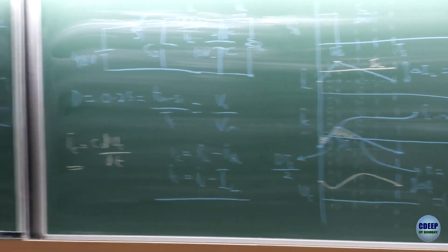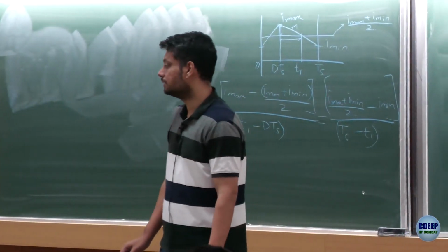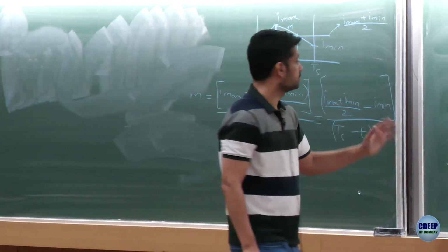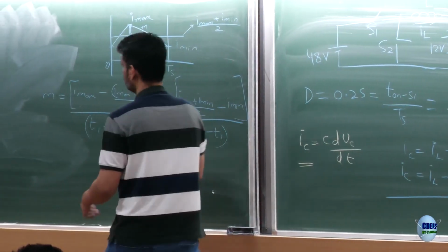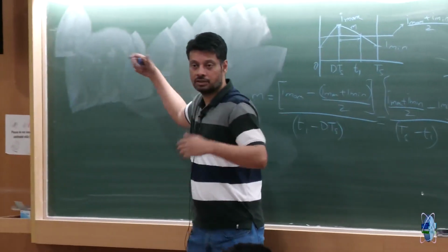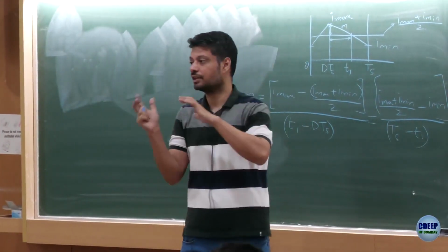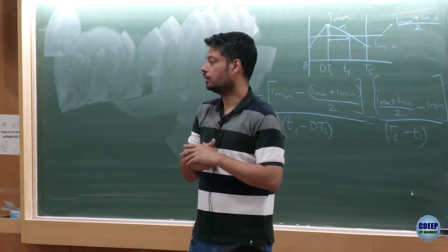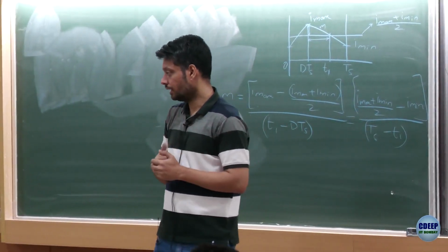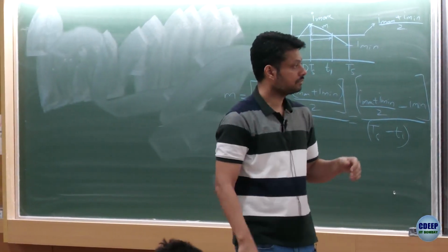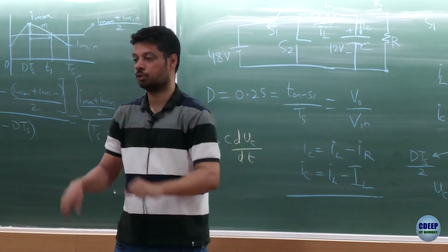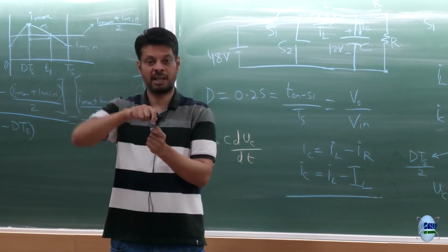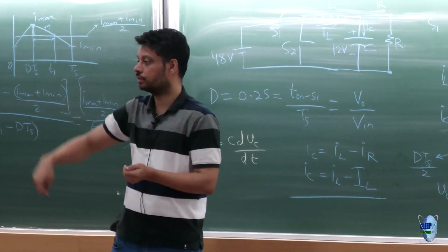Before you find the expression, let me tell you why finding delta Vc is important. Because there is our, we erased it. There was a 48 volt battery, there was a DC to DC converter, and that is what was going into a horn, light, fans and so on, right. Imagine this guy has an output voltage ripple of 5 volt. So you have 12 volt, but output is oscillating 5 volt, right.